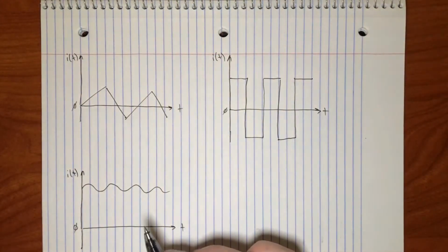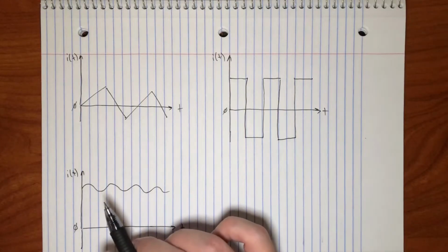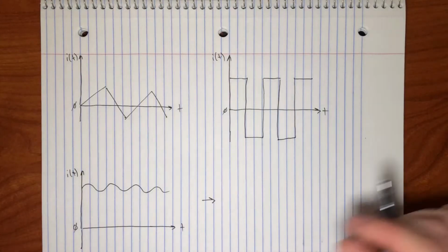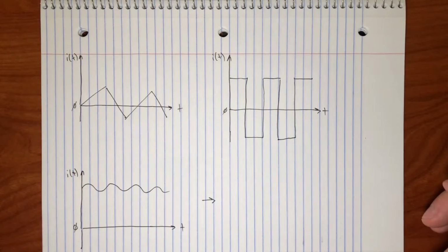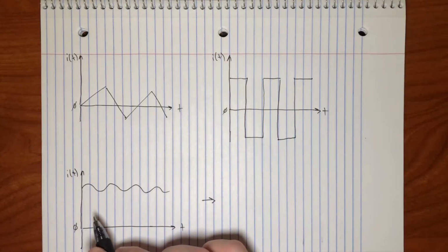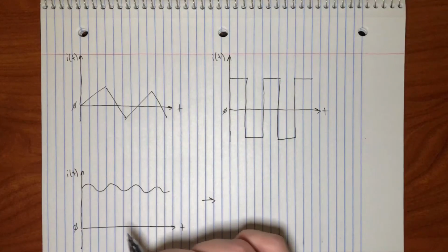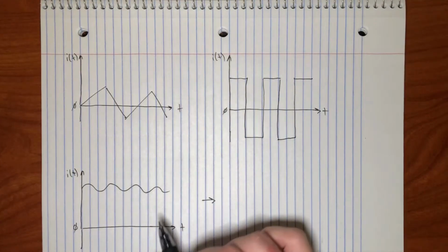So like I was saying, this is just one example of a current that it doesn't necessarily make sense to describe as AC or DC alone. And so this leads me to a technique, or rather a perspective, that you as an electrical engineer should have when you look at circuits, when you look at current, when you look at mathematics, and that's to see when and where you can apply principles of linearity and superposition. So if you look at this current, you can see it for what it is as a whole, and it may or may not be valuable to you to analyze it that way. But something that's usually incredibly valuable for an engineer to employ is, like I said, the principle of superposition. So you can look at this current and see it for what it is, or you can describe it as the combination of other currents.